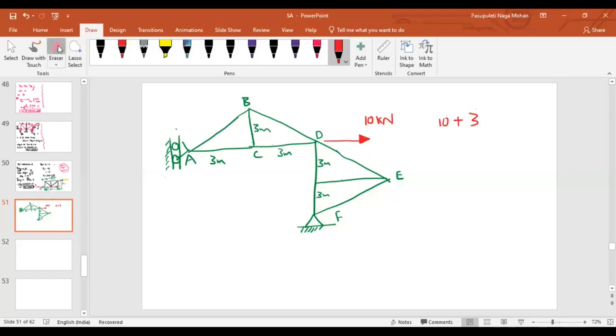No, here the thing is that I just gave some random truss. So here we cannot directly find the reactions. Why? Because here 10 kilonewton is acting like this, isn't it? So this will be balanced by the horizontal reaction generated here and the horizontal reaction generated here, isn't it? Yes, sir. Can you tell me how much portion it will resist here and here? Out of 10, 5 will take here, 5 will take here. Can we quickly judge it by looking at this truss itself?